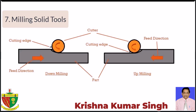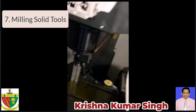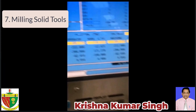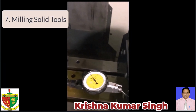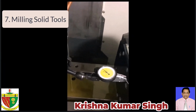Some people may not know what backlash or runout is, so before moving forward, I want to explain them. Backlash or play refers to the clearance or loss of motion in a machine caused by gaps between different parts. For example, if a CNC machine moves in the positive X direction and then the program changes its direction, the machine usually loses a couple of microns, resulting in movement short of the commanded value.